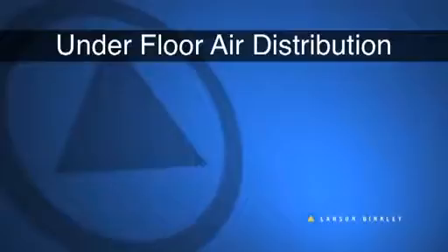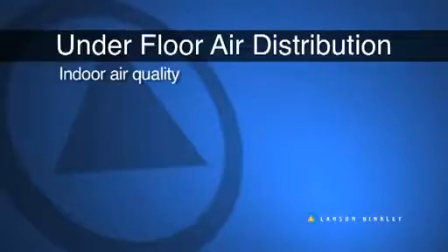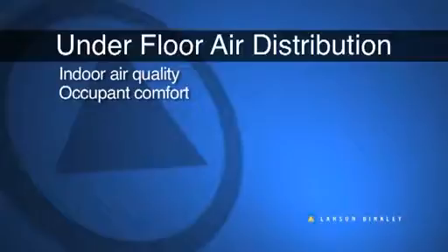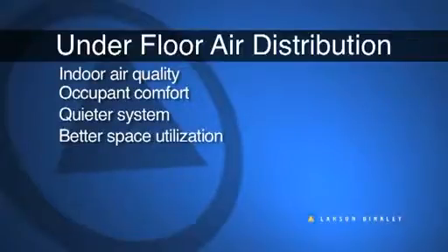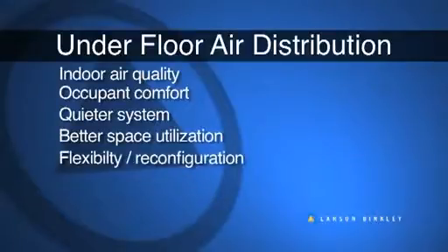To recap, here what we see are the driving factors why underfloor air distribution is worth considering. Indoor air quality is greatly enhanced over mixed systems. Occupant comfort is greatly enhanced. It's a much quieter system. Better space utilization is possible. The flexibility of reconfiguring the space is a big plus in today's office environment.